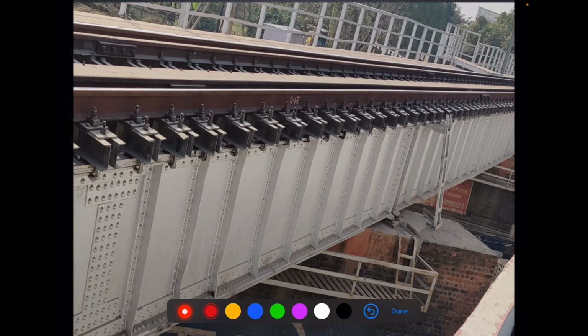So actually in the field, this is how we fix these steel channel sleepers on plate girders or any other girder. So these are the channel sections built combined together to form a steel channel sleeper. So these are all steel channel sleepers. This is the running rail. This is also running rail. In between we have these two guard rails and these are the holding down bolts.